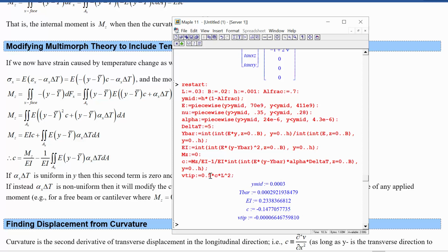and that's not that much, but the length to thickness ratio is only 30. In an actual strip, a more realistic set of dimensions would be making it about the thickness of a decently thick piece of paper. So that's 200, let's say 200 microns, and coiling it up so that the length is like 30 or maybe even 30 centimeters long. Now for a 5-degree increase in temperature, you can get the tip to move by 3 centimeters. And that's a pretty big displacement that you can detect macroscopically.